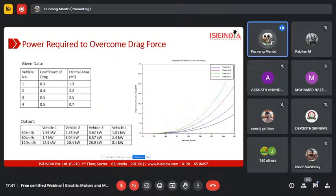I have done a simple example using MATLAB. I took 4 cars with 4 different drag coefficients and 4 different frontal areas, and I looked at how the power is going to increase with respect to the speed of the vehicle. You can see that vehicle number 3 has the highest coefficient of drag, and it has the highest frontal area, 2.5 meter square.